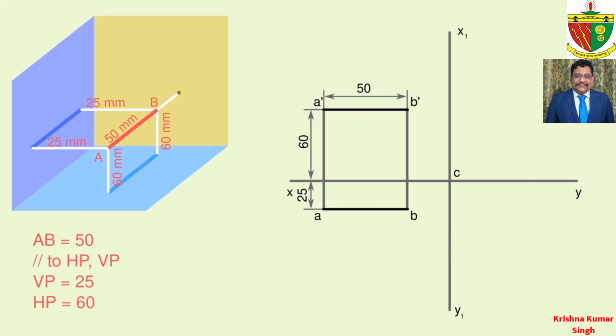For the side view, take x1y1 line which is perpendicular to the xy line. Consider the line of intersection of xy and x1y1 as C. From the top view, extend the light line until it touches the x1y1 line and name it as P. Now take the compass and C as center, P as the distance, draw an arc until it touches the xy line.